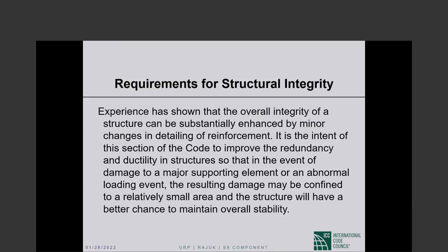The spacing between longitudinal bars and so forth is what I was talking about. The spacing of the transverse reinforcement, this is where requirements are relaxed from what they are for the columns of the superstructure.